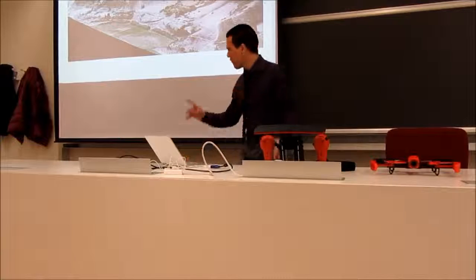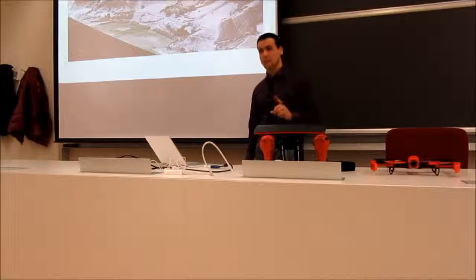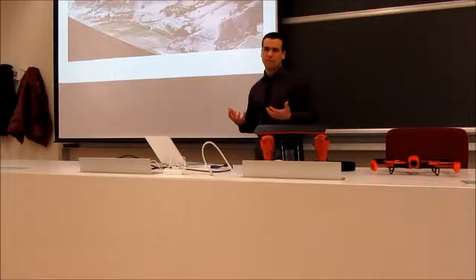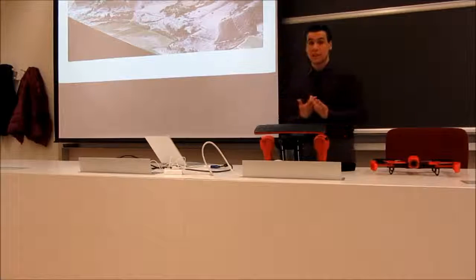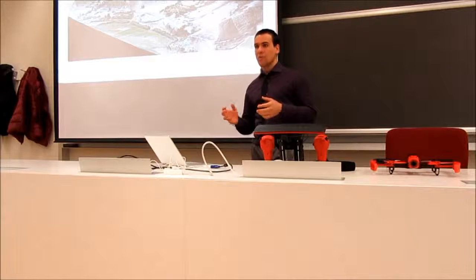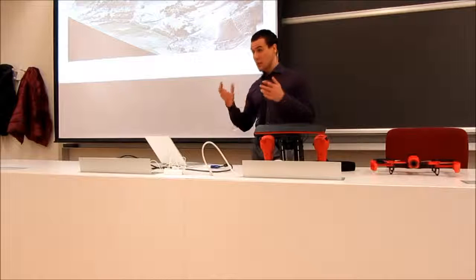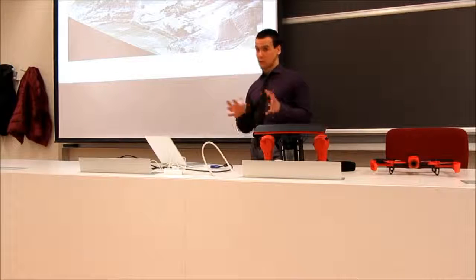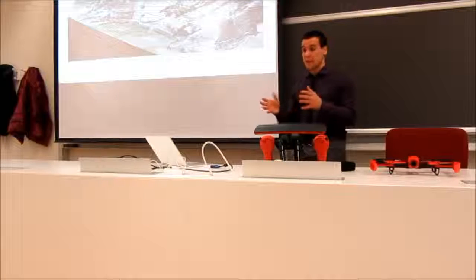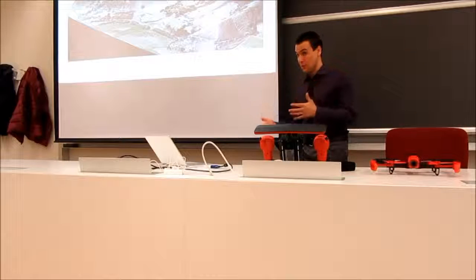And yes, now this is the slide about 3D mapping, but I would also like to add something. For ENAC, the main authorization is the non-critical authorization. You can fly in a non-critical zone only if you have ENAC authorization. If you don't have it, you have to request the authorization from ENAC. Otherwise, you cannot fly for commercial purposes. If you need to fly in a critical zone, so you have to do a critical operation, you have to ask for another kind of authorization.